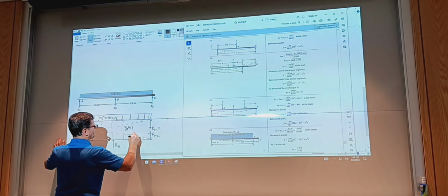So again, assuming this is given, I can analyze the two because they're documented in the back of the book as formulas, and then to get the resultant deflection, I just add them. You can add them throughout, and you state the equation of the deflected beam or at the locations of interest.